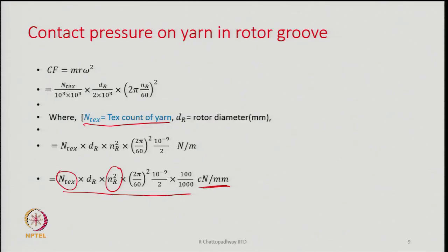So, anyway, these are the different aspects that we learn from here. The pressure itself is also important, because too much pressure will not allow the twist to penetrate into the groove, and because of this it can also lead to end breakage, because the fiber band in the groove is not getting twisted, as the torque is not in a position to reach the groove.